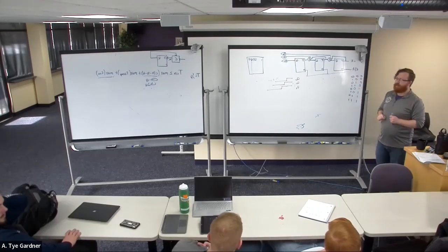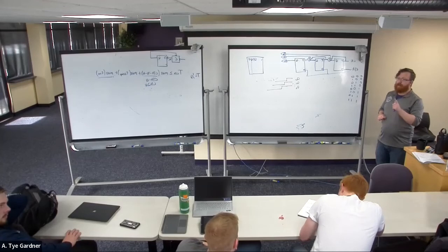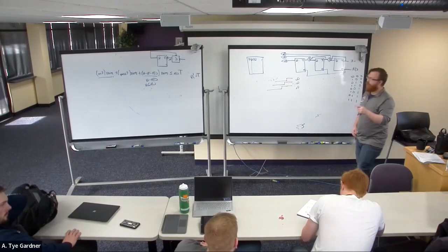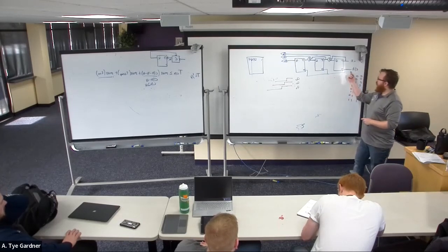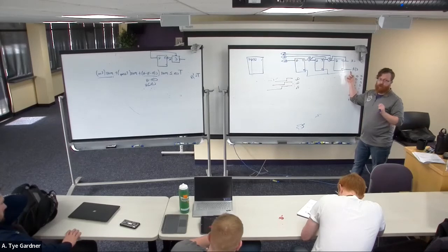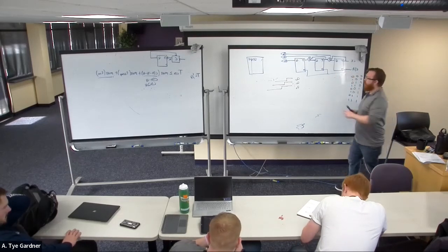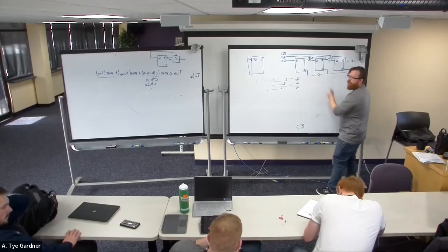Yes. So if you don't care about going faster necessarily, but you want to keep it accurate, you can just put buffers in. The buffers come in. We do need buffers every once in a while. So if I start cascading a whole bunch of these together, eventually this clock signal is not going to be powerful enough to drive. That's what we call it. We won't be powerful enough to drive all of those flip-flops. So eventually we would sever this and put a buffer in.